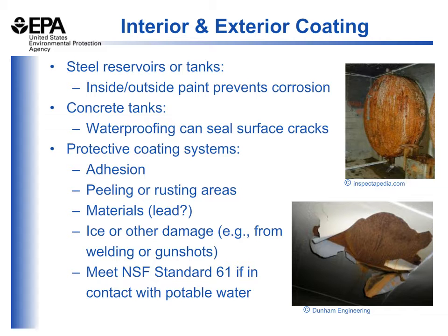The steel tank coating is covered under the American Water Works Association standard D102-97. And if you have an older tank, you may want to think about having the paint tested for lead before any work is done or paint is removed.